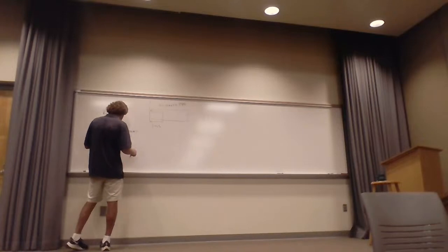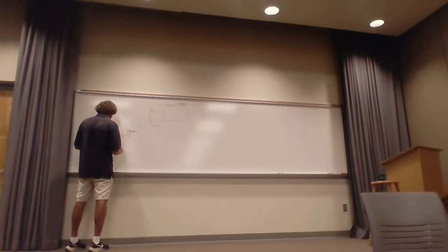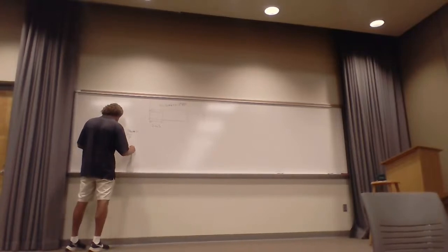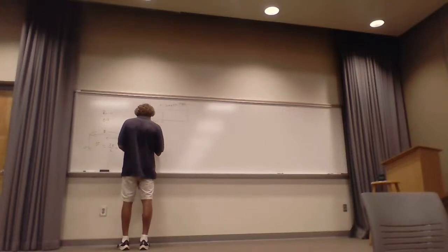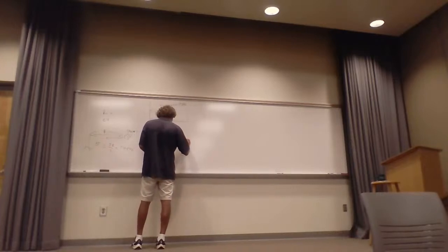And there's other ways. So anyway, if you say this, that means that would be T, or the PRI, the pulse repetition interval. And therefore, that range R, we call the maximum unambiguous range, would be equal to C tau, or C times T over 2, or C times the PRI over 2.